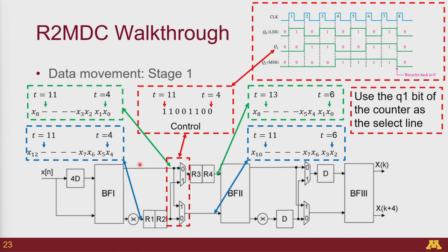So generally, it depends on what we are doing. In this simple case, since it's cyclic with 2 and we are shifting by 2, that would just mean inverting the signal. But let's say you're shifting by 1. You could either implement a delay to shift that bit, or you could have a condition which would be set high when certain values are hit, like a normal switch. Let's say if the value is equal to 1 or 2, then set the value high, otherwise set the value low.